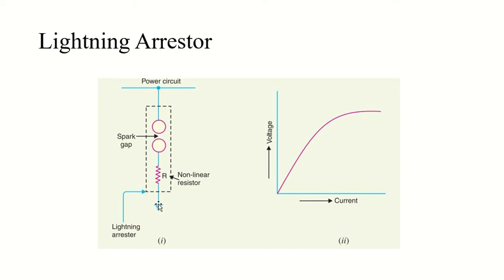Secondly, the IR drop, where we are considering the surge current as I, across the arrestor when carrying surge current should not exceed the breakdown strength of the insulator of the equipment to be protected. Right? If it exceeds that breakdown strength, then there is no point. It's pretty much self-explanatory.